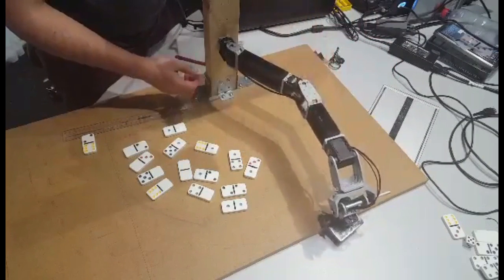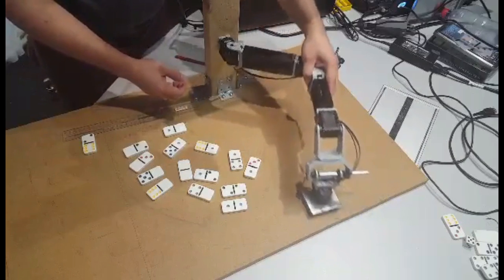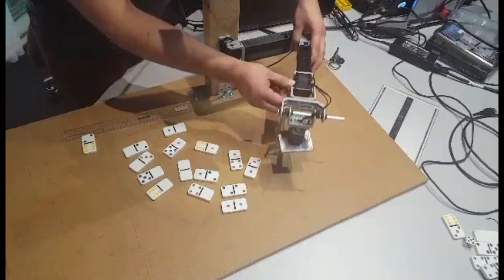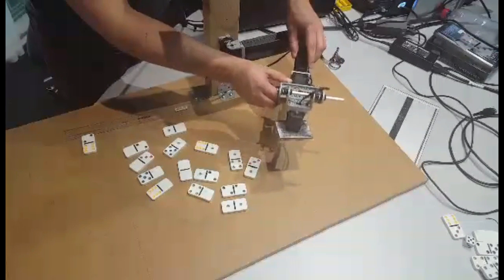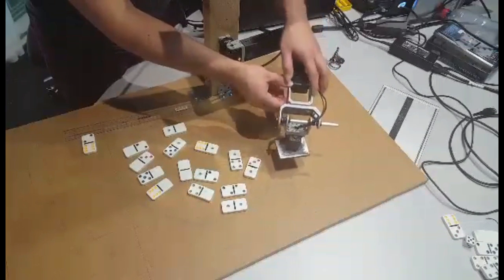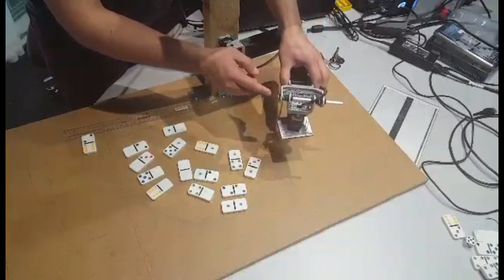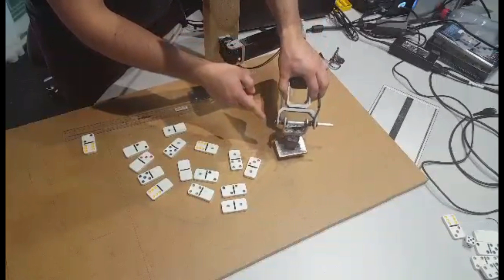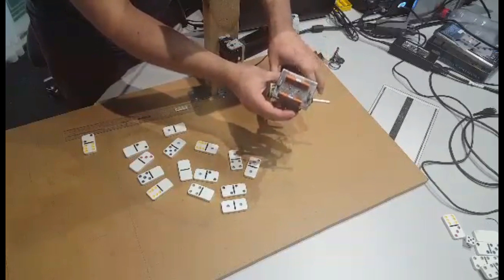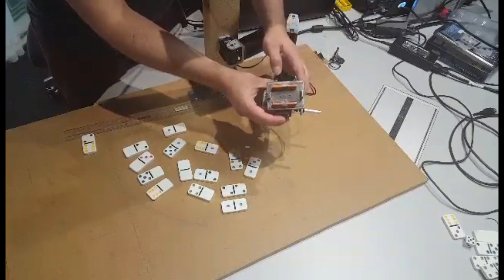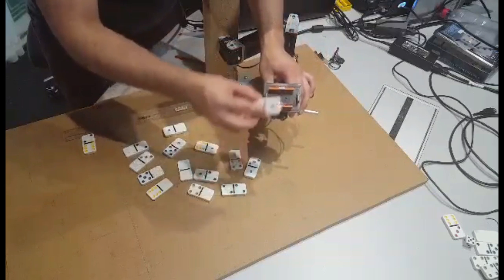The third motor is used for controlling the end effector's height, having the third link attached to it with a free rotation joint, which allowed for the angle adjustment of the end effector posed by gravity. Finally, the end effector geometry corresponds to a domino housing tool with the fourth motor rotation axis along its centroid.